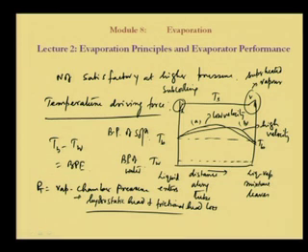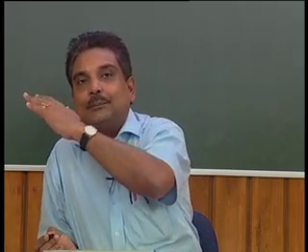So it does not boil at this point, and its temperature rises, and then it may be that it boils here. Once it starts boiling, the temperature reduces, because it is going upward, the hydrostatic head gradually decreases and the boiling temperature reduces.